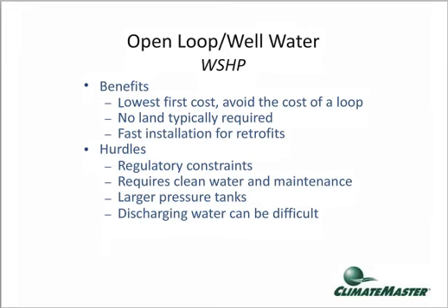It requires, and I want to emphasize that, it requires good water and will bring some maintenance involved. Sometimes you have to increase the size and or quantities of the well pressure tanks. And you always need to ask this question, where are we going to discharge the water when it leaves that heat pump? Because you do have to deal with that. Don't overlook that.